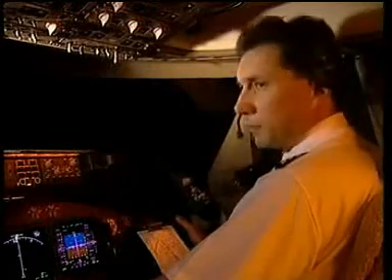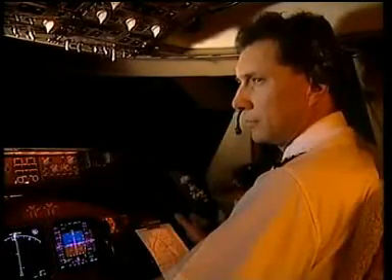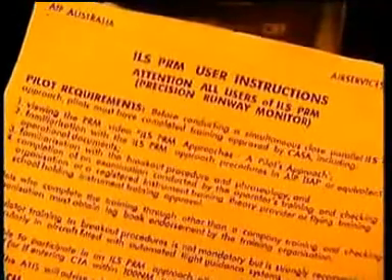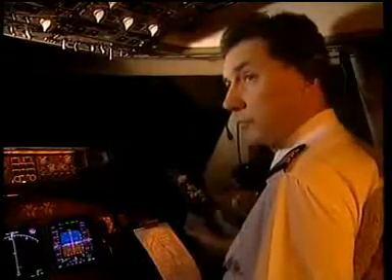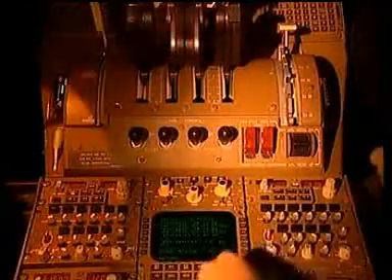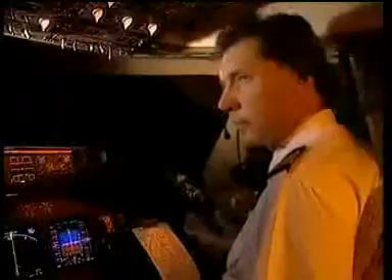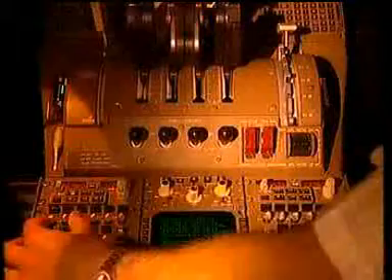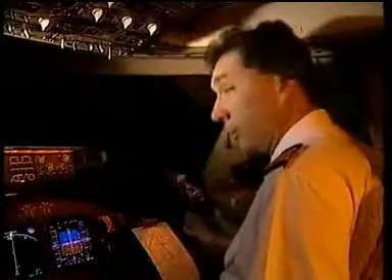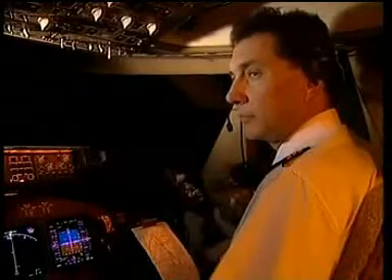Any questions? Is it possible to get a descending breakout? That's unlikely, but if we have a descending breakout, we will not be required to exceed a rate of descent of more than 1,000 feet per minute. Okay. The ILS PRM user page also specifies that the COM procedure is that when instructed by ATC to call the tower, we must have the tower on number 1 and the PRM frequency on number 2. We will only transmit on number 1 and we'll have to set the volumes about the same. So we just monitor the PRM frequency on the second VHF COM? Yes, that's just in case there is a breakout instruction which is blocked by a transmission on the tower frequency.